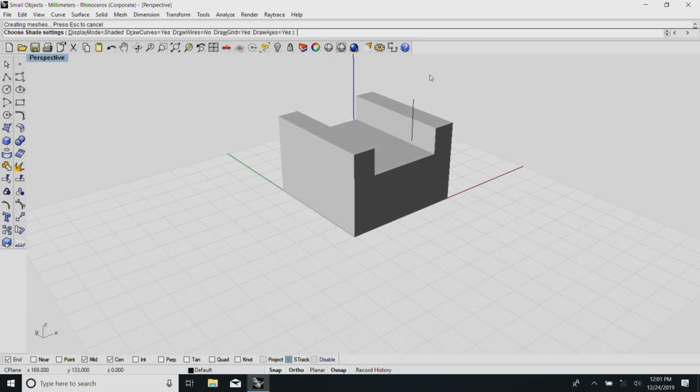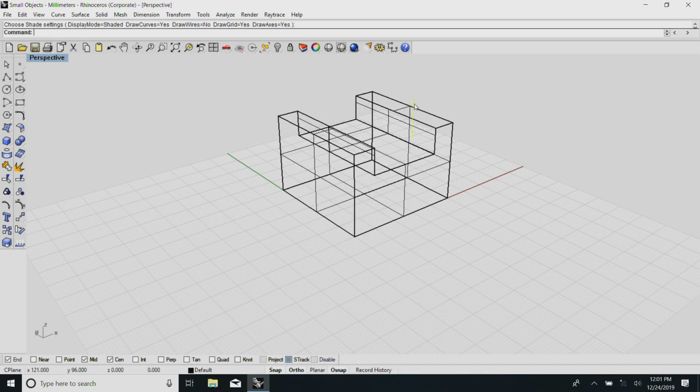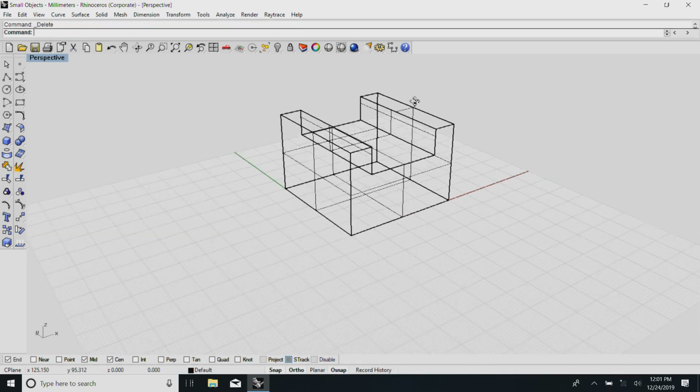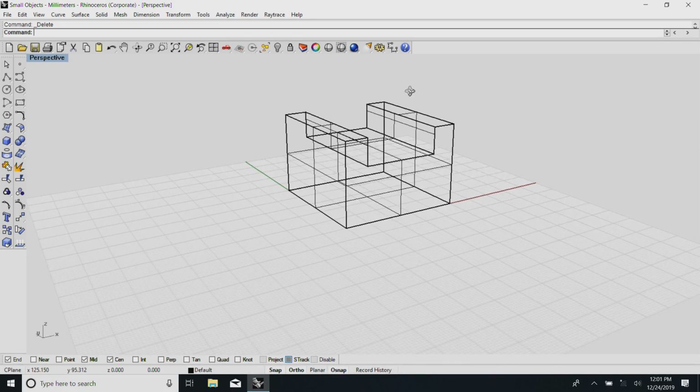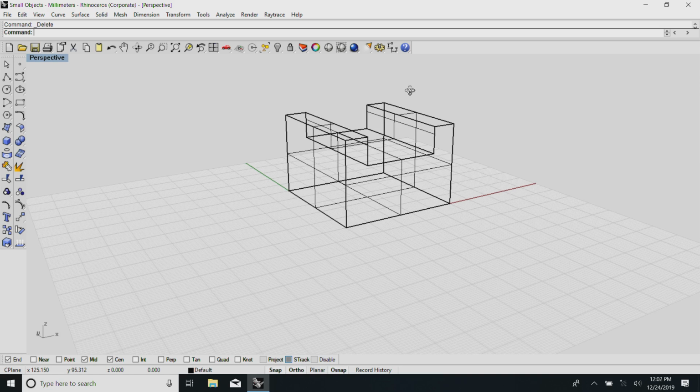Several advantages it has. First of all, it is perfectly to scale. Second thing is it follows a little bit of the operation sequence which we do in the workshop. Now, there needs to be a groove at the bottom, and in this case I have measured it out and it requires a hole of 22 millimeters.